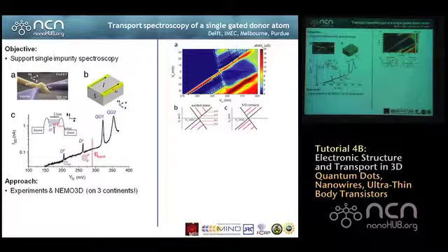And if you're in this field, you would recognize that immediately as a Coulomb blockade diamond. Okay, and Coulomb blockade diamonds are indicative of single electron charging effects. Here is a Coulomb blockade diamond, and there are these streaks on the side that run away like this. These streaks tell you something about some of the details of the structure that you're tunneling through. There can be two things. It could be effects of the leads, and it could be effects on the inside of the device, meaning the impurities. And in fact, these are excited states of these impurities.